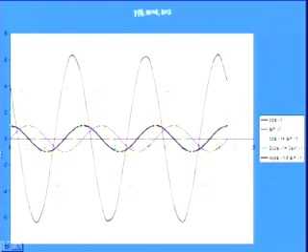You see the motion starts, the displacement goes up to a distance, then goes down by the same distance, then goes up again by the same distance. The time it takes between cycles is also the same, and the displacement it covers is also equal. That is what I said: when we do not have a damper, the motion will go on forever with equal magnitude.